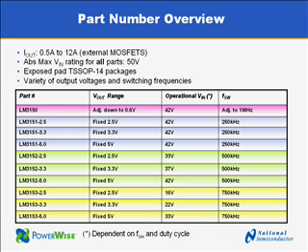So from 40 volts you cannot reach down to 2.5 volts at 500 kHz. Simply not enough time internally. That is the limitation. The part withstands 50 volts absolute maximum rating, no problem, but operational 33 volts. And that's the same for the other parts, like the 750 kHz parts that do not reach the 42 volts operational.